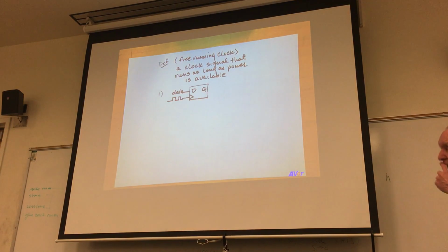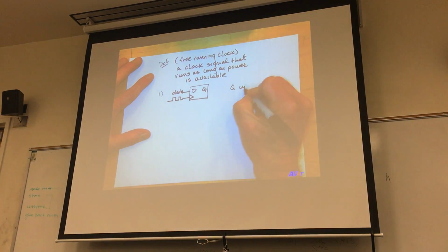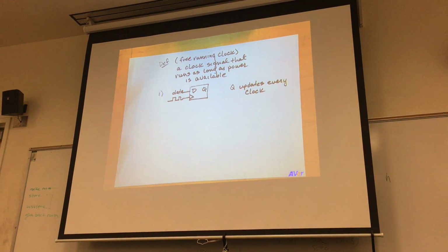In this circuit here, your Q output is going to update on every clock. Well, maybe in your design, you don't want to do that. Maybe there's only certain periods of time in which you want Q to update on a clock pulse.